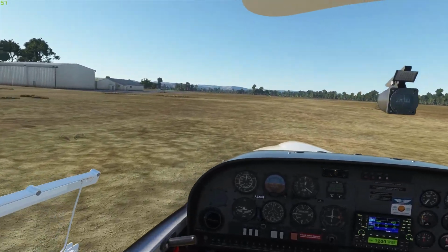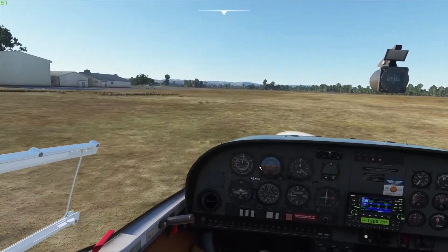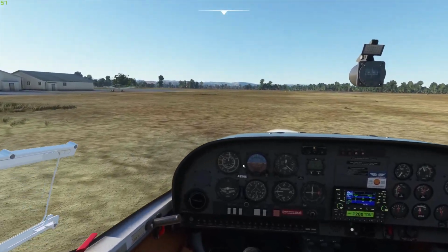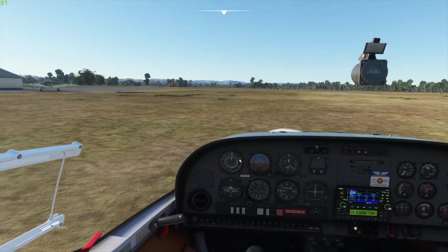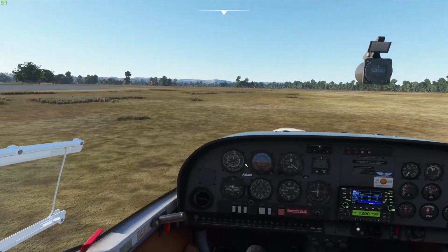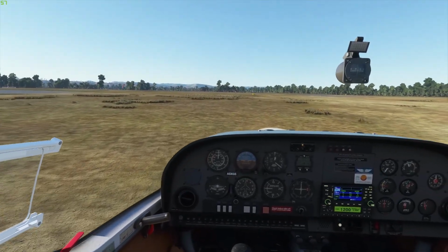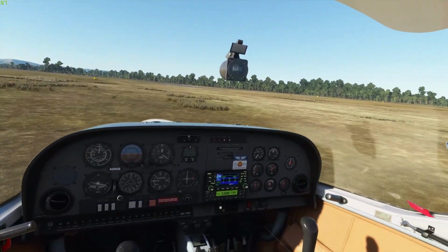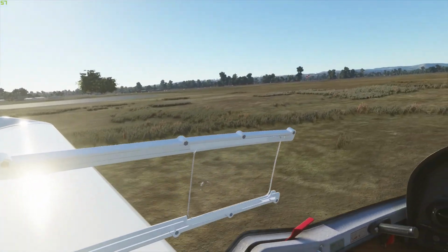Okay, so having never flown this aeroplane before, all I've got to go on for the stall and low speed characteristics is the bottom of the white and the green arc here on the airspeed indicator. But I don't really know how it's going to fly and how it's going to stall. So the safest thing to do is just fly it fast. So I'm not going to rotate as soon as it gets to 40 knots. I'm going to probably go somewhere between 50 and 60 knots before we try and rotate the aeroplane off the ground, and that just makes sure we've got plenty of speed above the stall to fly away cleanly, and we can go and investigate that a bit more closely once we get up to altitude. So we're all clear on the left.